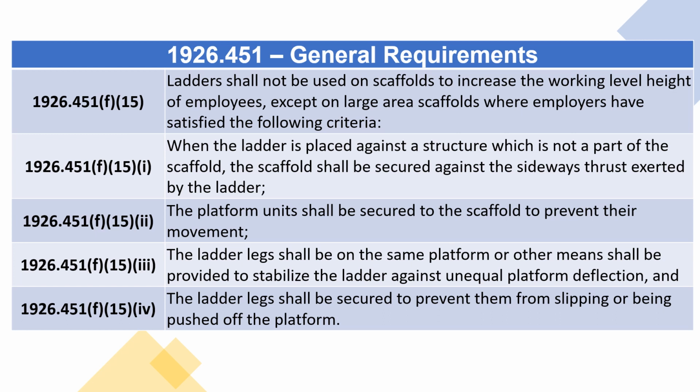The platform units shall be secured to the scaffold to prevent their movement. The ladder legs shall be on the same platform or other means shall be provided to stabilize the ladder against unequal platform deflection, and the ladder legs shall be secured to prevent them from slipping or being pushed off the platform.